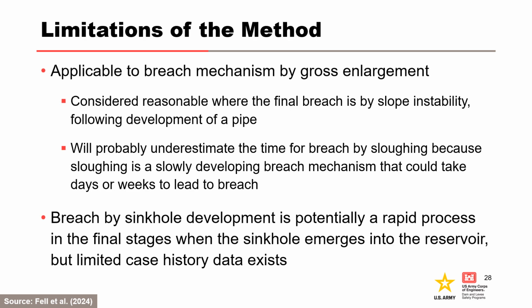This slide shows the limitations of the approximate method. Most of the case studies were for breach by gross enlargement, and therefore the method is really only applicable to cases where the breach mechanism is gross enlargement. The method is considered reasonable for final breaches by slope stability following development of a pipe, but it will likely underestimate the time for breach by sloughing, since breach by sloughing is a slowly developing mechanism that could take days to weeks to lead to a breach.